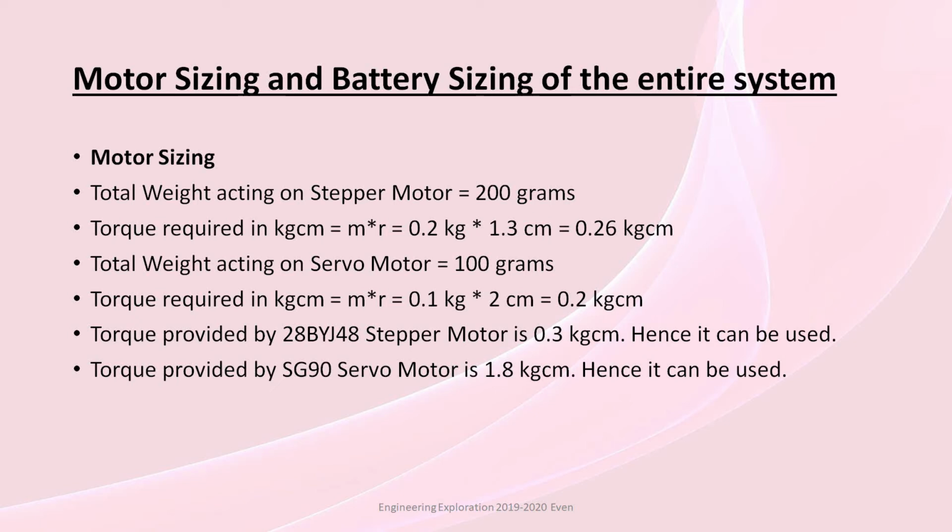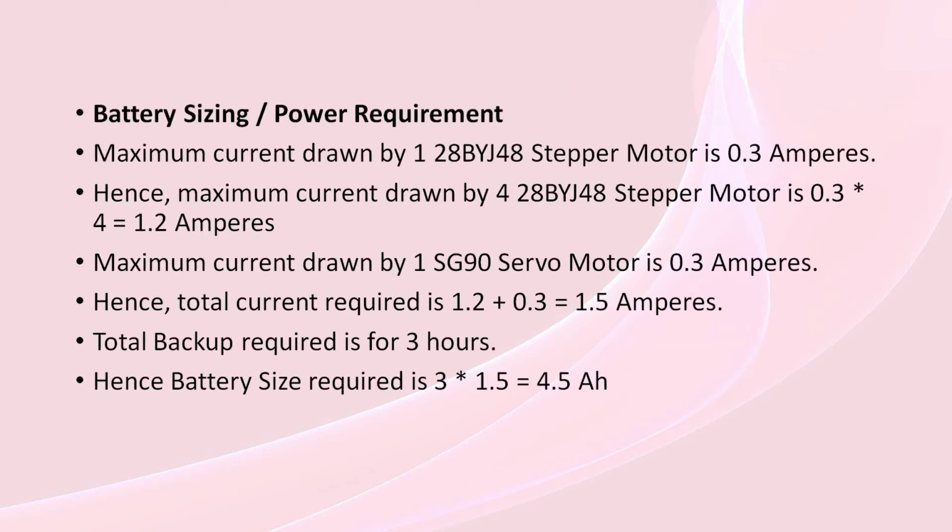The total weight acting on a stepper motor is 200 grams, so the torque is 0.26 kg centimeter. Torque provided by the stepper motor is 0.36 kg centimeter, hence it can be used. Now we will see battery sizing.